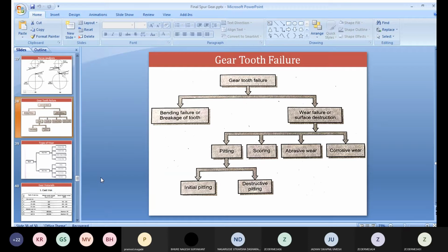While the gear is touching the teeth of the pinion, it will remove the material of the other surface, and then moving toward meshing again in another cycle, it will stick there, again remove, again stick. So this is for every tooth. Due to that, this stick slip phenomenon will form a number of cracks over the surface of the teeth. Due to that, failure occurs. All this process is called scoring, galling, or scuffing. हे कळालं का रे?